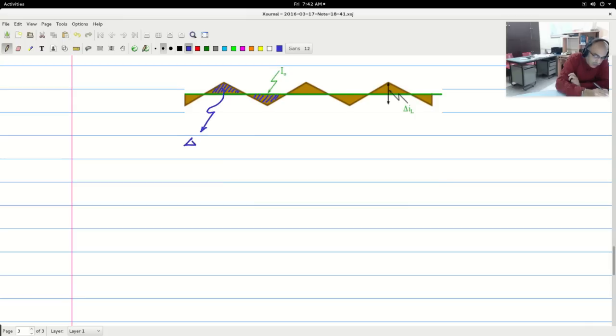So this will be delta Q. Now looking at the capacitor waveforms, we know that this is the time the inductor current has magnetically charged up. So this is dTs, and this is the time when the inductor current is falling with a slope of minus V0 by L, and therefore this has to be the 1 minus d Ts period.